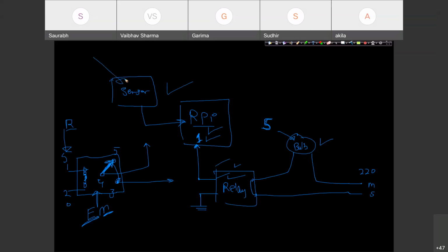In real, this sensor is taking a real-time parameter from the environment in terms of sound, converting it into an electrical quantity. That electrical quantity from the sensor itself, through the comparator, is converted into a digital signal. And this digital data is getting inside this Raspberry Pi. This Raspberry Pi is processing that data using Python, and it's taking action on the relay to control the bulb. So this was the pipeline overall from here till there.